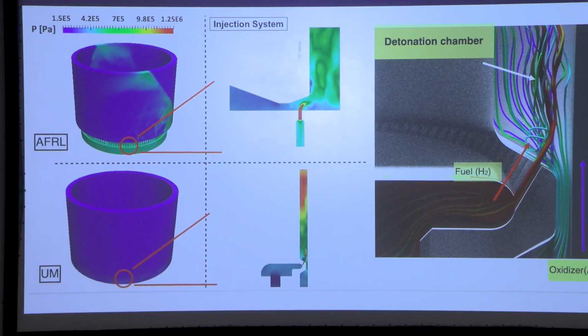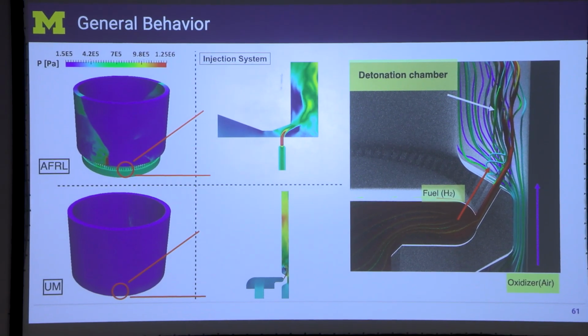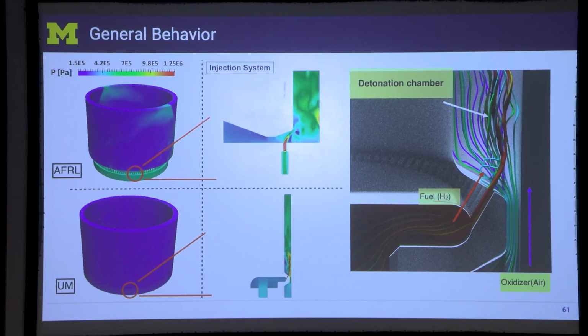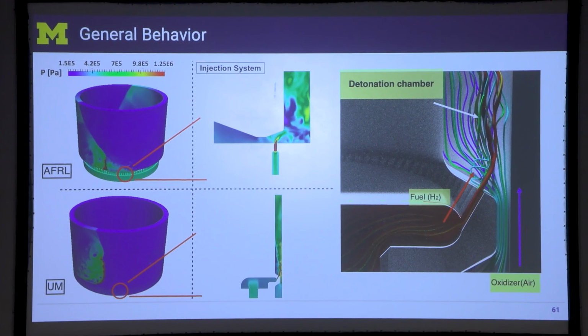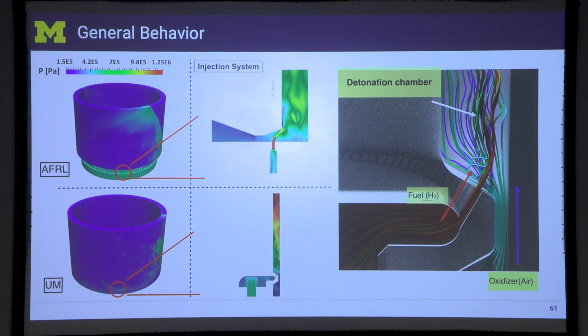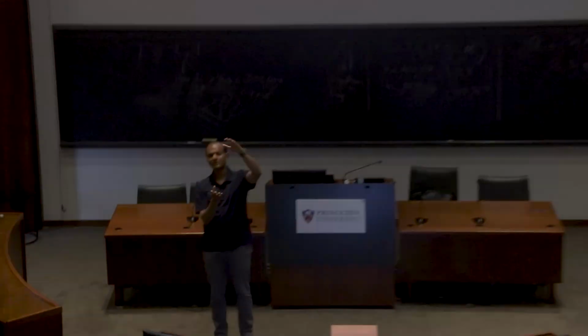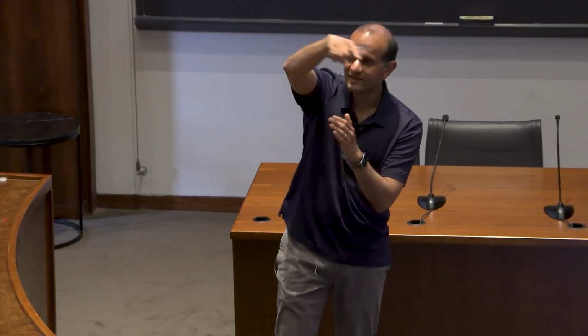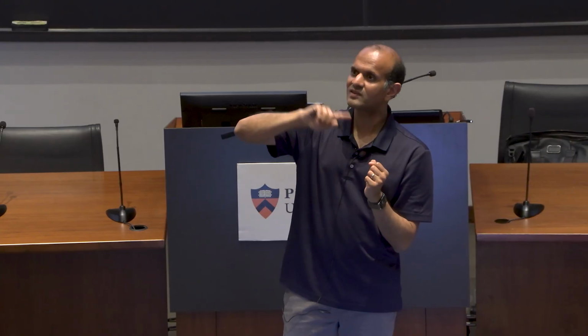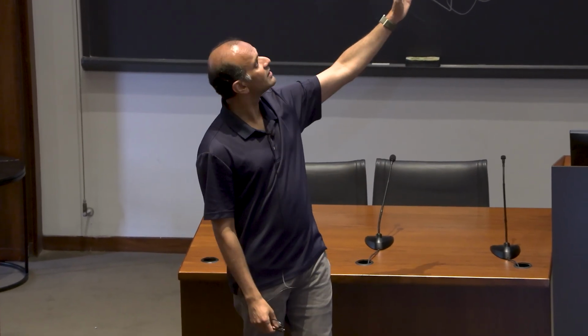It turns out that it's a lot more complicated than this. So you have to inject fuel and air. You have no option about it. That's how you design any kind of propulsion system. But as you inject this fuel and air, there's a detonation wave that moves over it periodically at very high frequencies. Okay? So when the detonation wave moves over an injector, because the pressure is so high behind it, it just blocks the injector. Now no fuel can come in, or no oxidizer can come in. So for a brief time during that cycle, there is no injection of fuel and air. Okay? And then the wave moves away, pressure goes down, and suddenly everything rushes inside to compensate. So you have this transient mixing process. You block the injector, you inject fuel and air, you block it again, you inject fuel and air. And of course, depending on the strength of the waves, how many waves you have, which direction they go in, all these complexities, that mixing pattern is super complex.